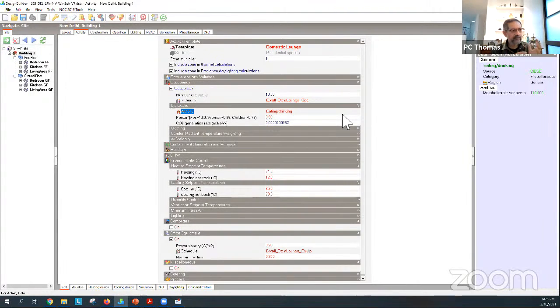It sort of says, okay, what's the total? And then depending on the temperatures on the inside and the outside and the relative humidity, it will work out what's the latent amount. Now, I would say that for residential calculations, that's enough. You don't really need to go any further than that. EnergyPlus has got a really smart subroutine to do that.